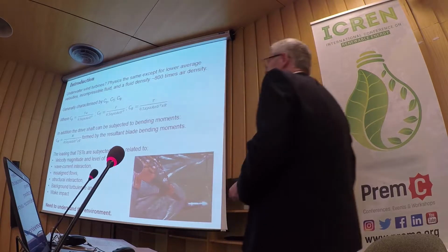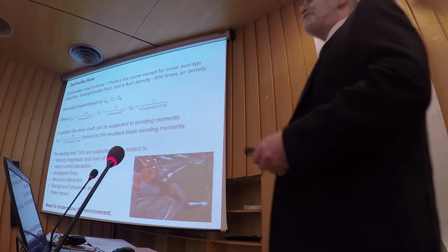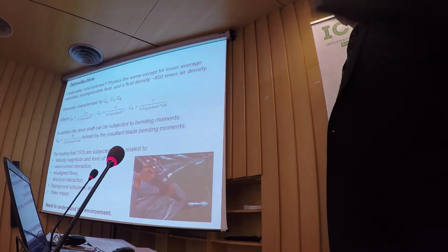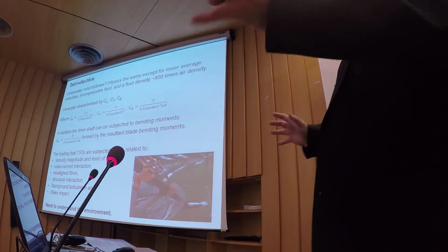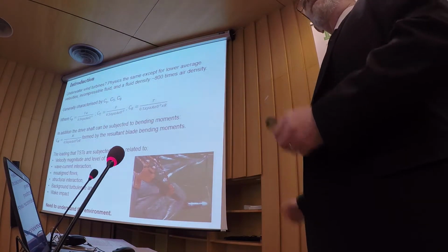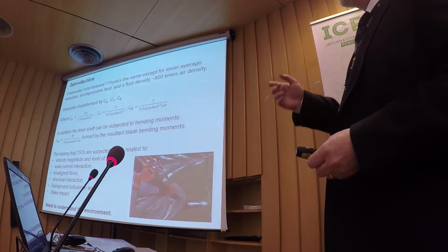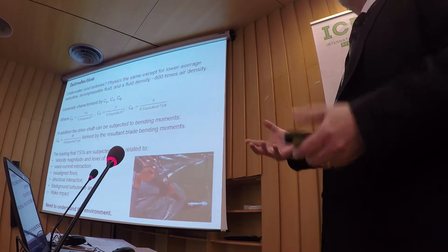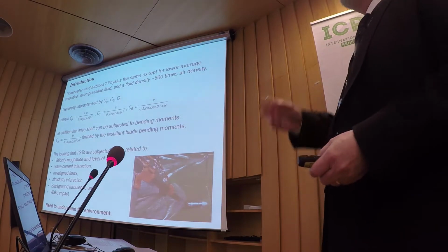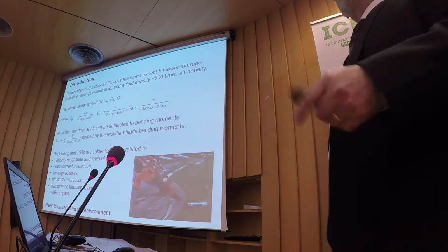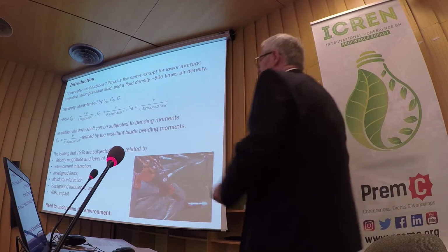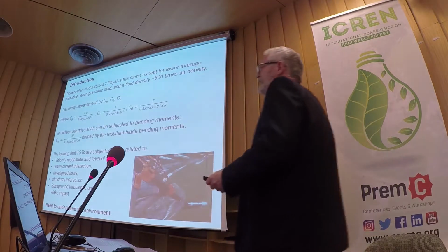Background turbulence. Well, turbulence comes in packages generally. Different sizes. You can get a decay from a very large scale down to the very small scale, and depending on what is hitting that turbine would depend on the influence it has on both loading and power output. And then you have the problem when you have a wake.